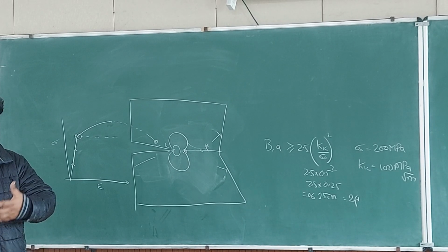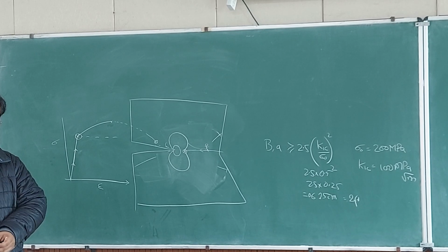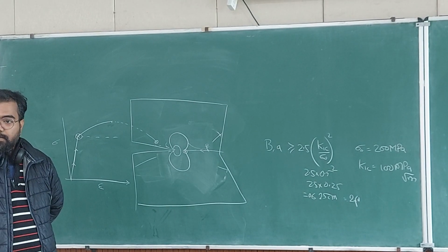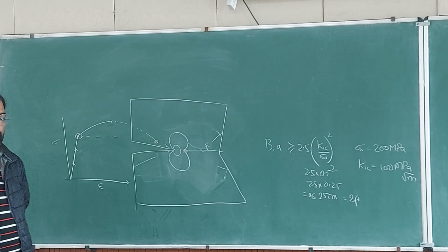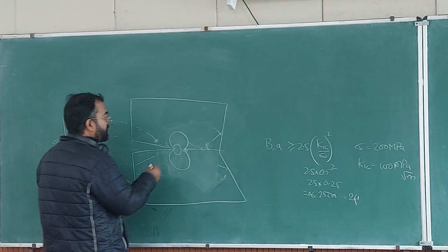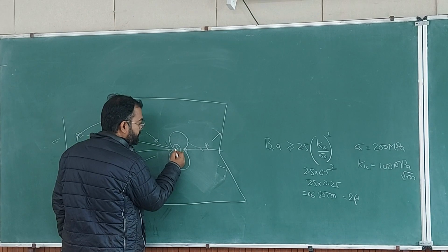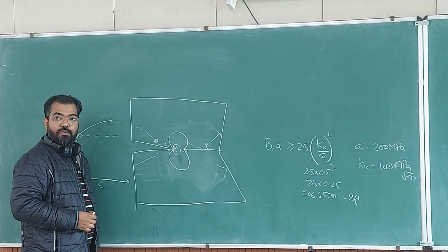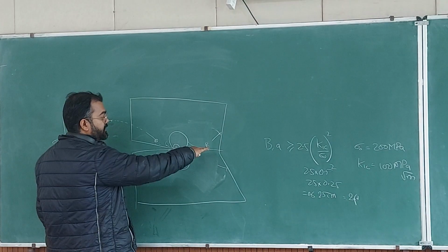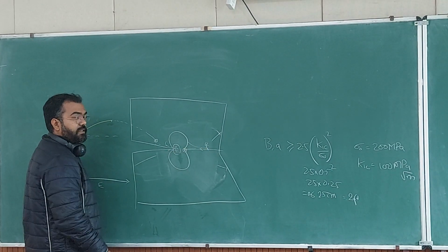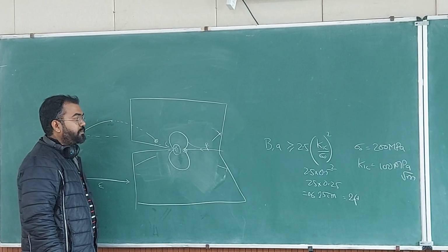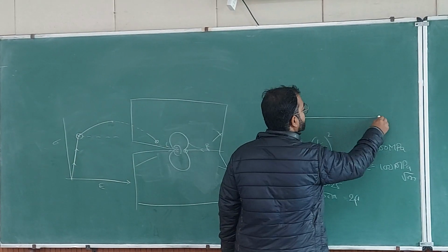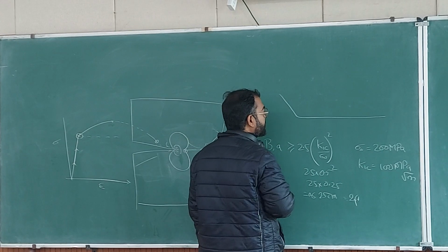What will happen? What is the phenomenon after plasticity? So this will be damage. Okay? So you will have a zone where you will have void formation. Okay? So now if you do a sectioning and look at it under a scanning electron microscope, then you should see a lot of roughness. It will not be flat as it looks.